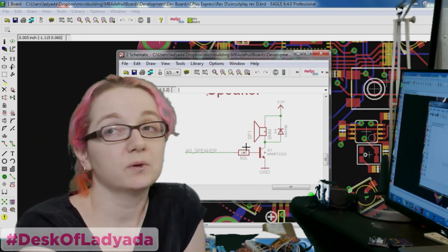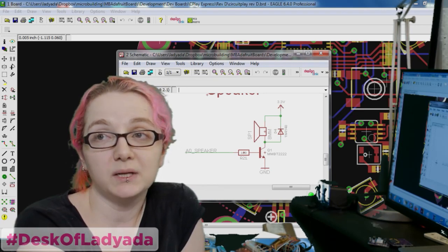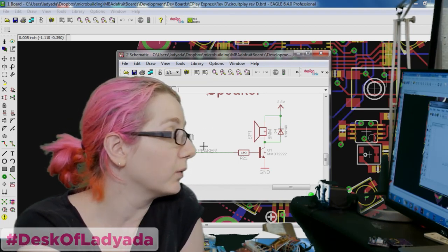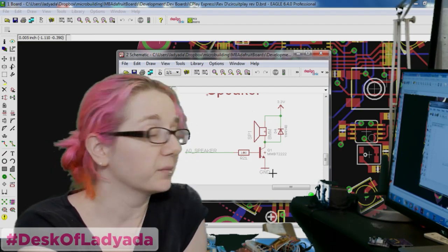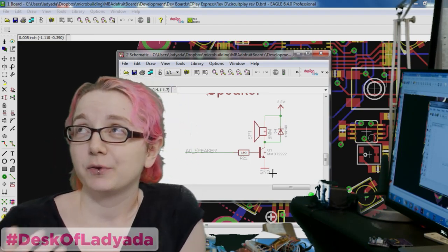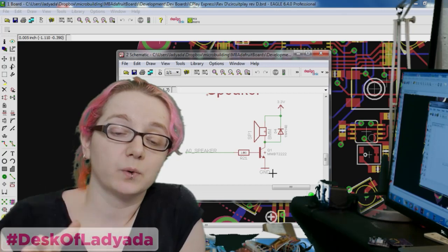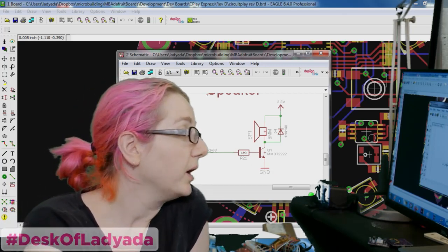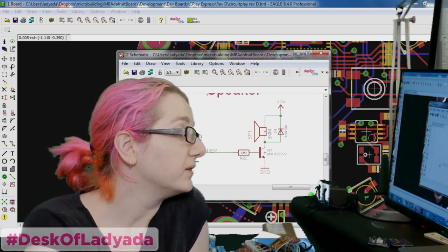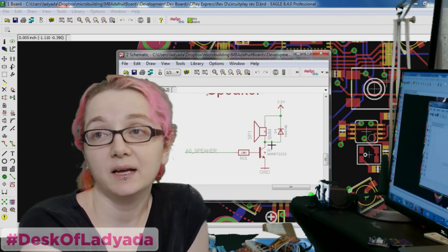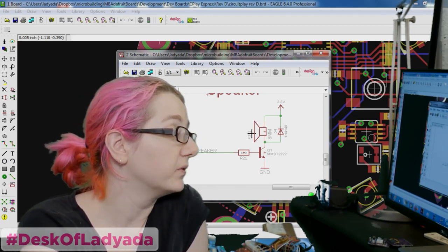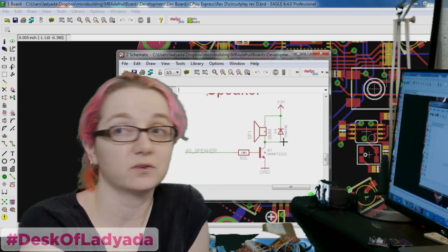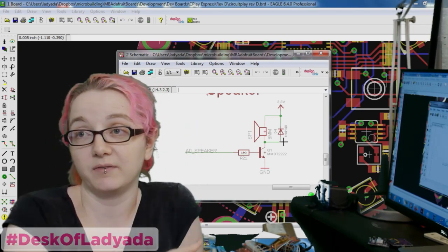If you connect this up to a timer and you're careful, it's never going to be an issue, because you'll have a square wave that goes high and low, which will connect this to and from ground. And for the most part, you toggle it and everything's good. The problem is it is possible for somebody to pull this pin high and keep it high, and this is like 8 ohms of impedance. This could burn out the transistor, because you'd be basically driving it with a DC load.